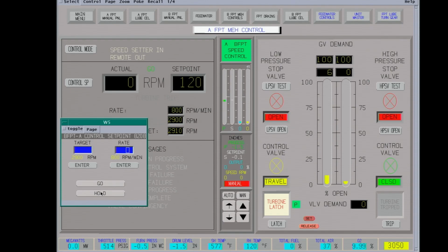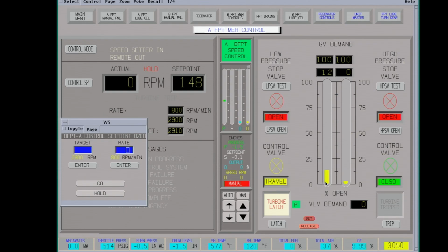We're going to have to hold because the set point's running up and your low pressure valve has to come full open first before it'll allow the high pressure valve. So there's no steam on this side, the low pressure. So we're going to rely on the high pressure steam. Otherwise this thing will wind up too high and then the valve flies open on you.